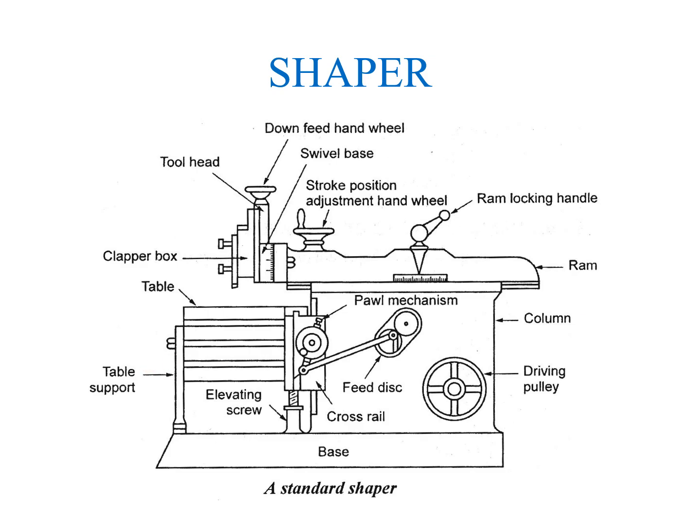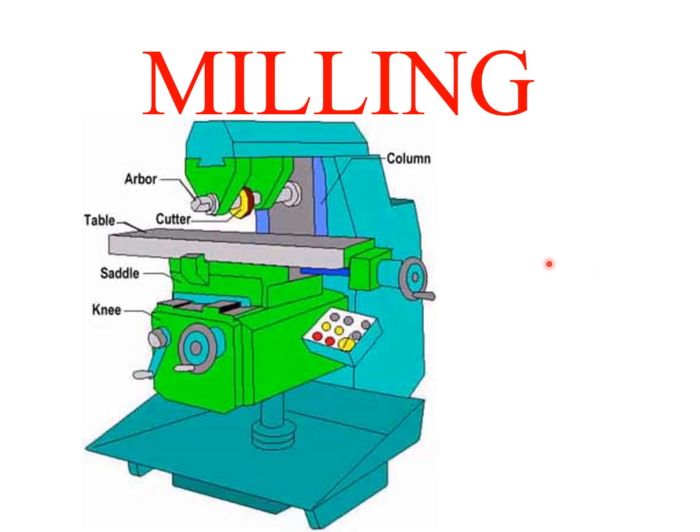Then milling machine. In general, milling is a cutting process that uses a milling cutter to remove material from the surface of a workpiece. The milling cutter is a rotary cutting tool, often with multiple cutting edges, as opposed to drilling, where the tool is advanced along its rotation axis. The cutter in milling is usually moved perpendicular to its axis so that cutting occurs on the circumference of the cutter.